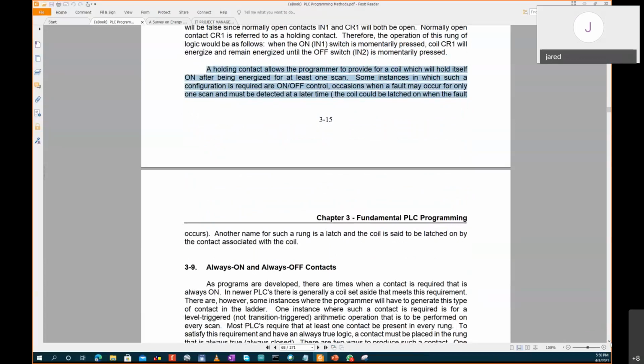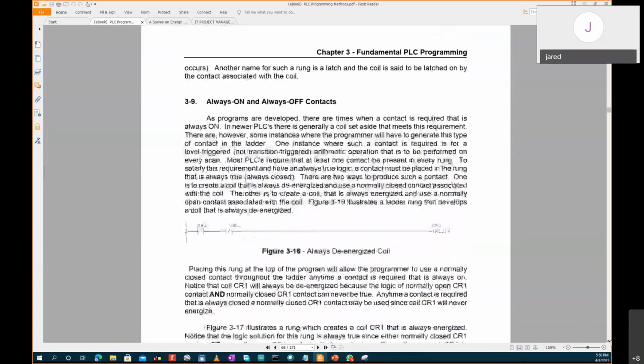So as we develop these programs, of course, if the PLC hangs and it has not done a scan run and the output is still active, that's a problem. So that's why you need to have those reset contacts in every rung, so that they provide some safety mechanism if there's a problem in the PLC.